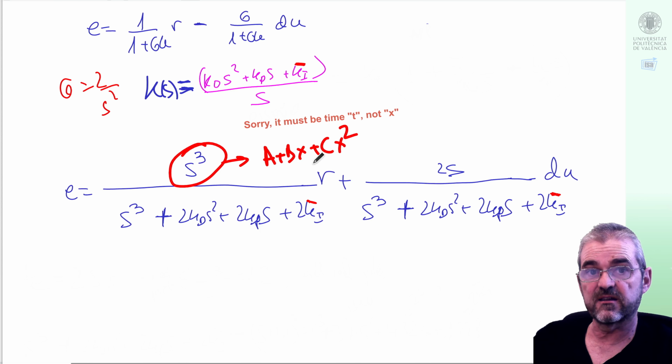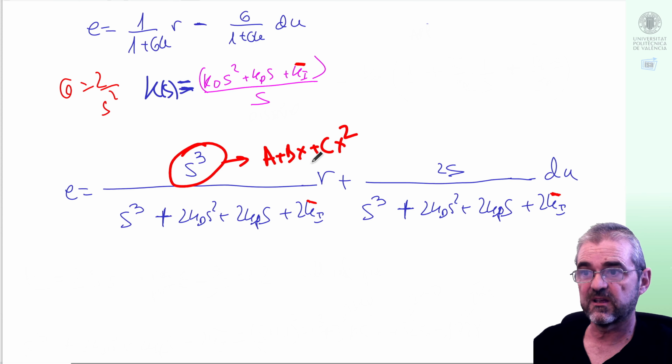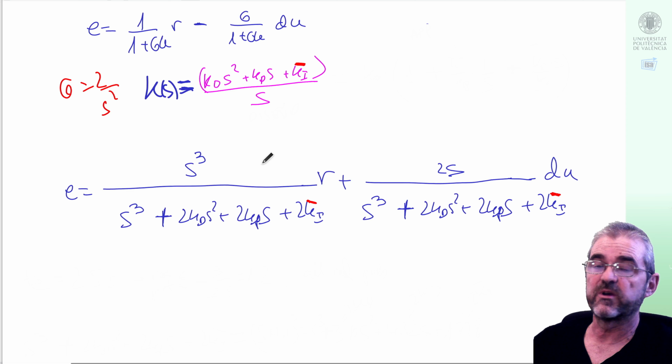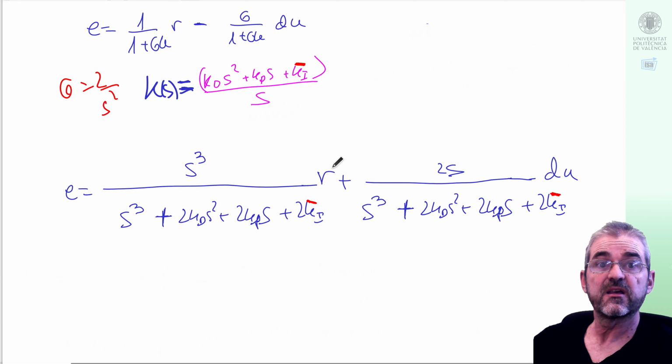In reference tracking, not only for constant setpoints, but also for ramp and parabola, so that would be the super good steady state behavior of setpoint tracking in this case, at least in theory. So good. We are then happy with our steady state error behavior, 0 error with step disturbance and setpoint.